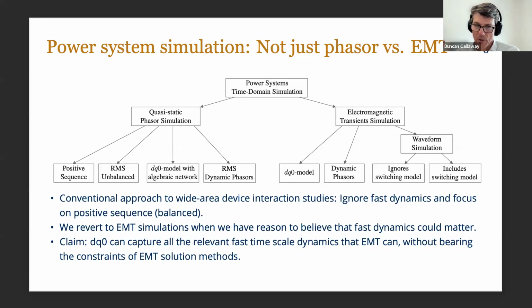And in that case, with inverters, you could either ignore or include the switching models of the transistors themselves on board the inverter. But then you can see, okay, we've got a whole lot of other things that sit in here for different kinds of simulations that one might consider doing. And the types that I'll be focusing on today are DQ0 simulations.